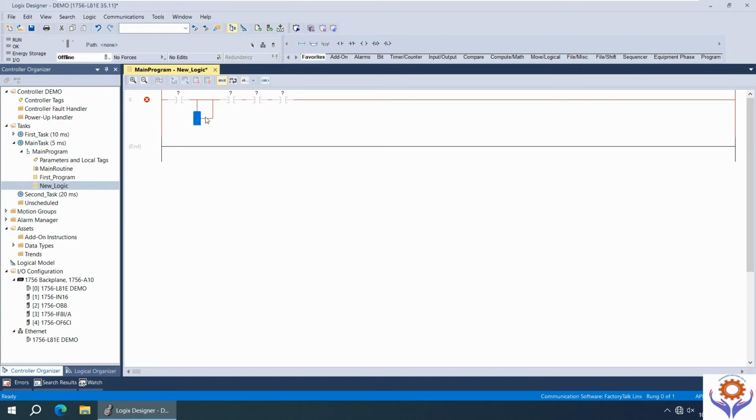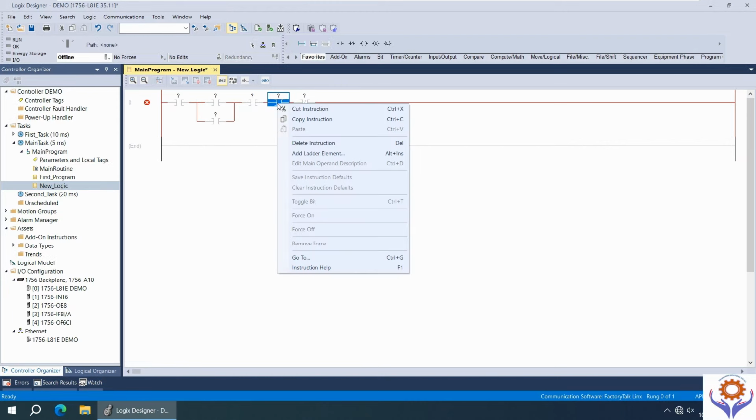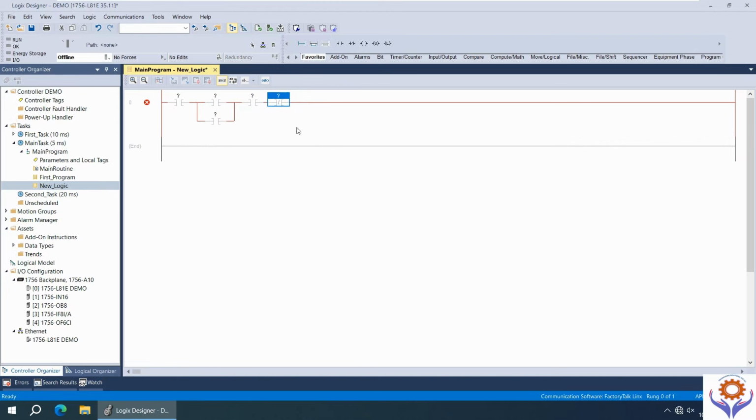But for this RSLogix Studio 5000, it will take a little time compared to other programming software. It will be a little bit tricky because you need to understand how to add. See here, this branch, sub branch. At first it will take some time, but if you practice, it is very easy to add. See, now I have already added normally open contacts and normally closed contacts. Now I am going to link the address tags.